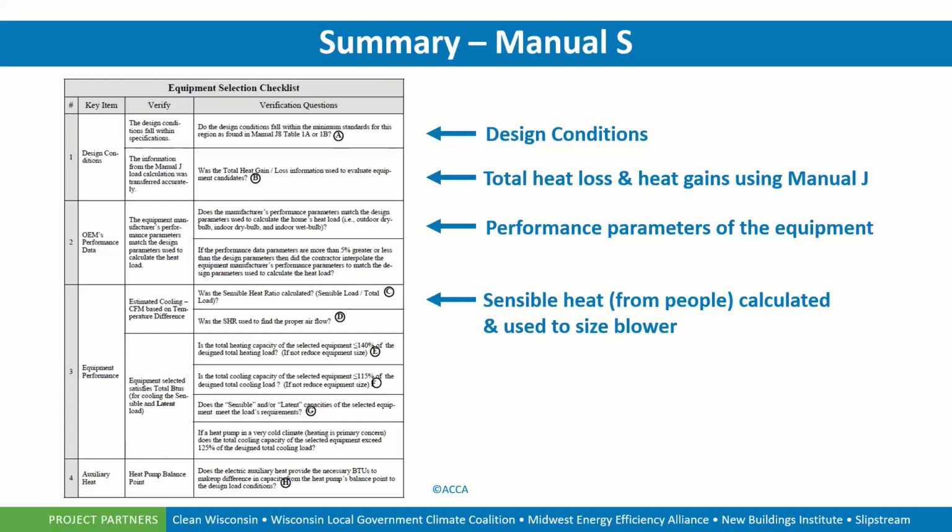So does our furnace, we look at the data for the furnace, does it cover our CFM flow? Does it cover our heating requirements? The same on our cooling side. We pick our heating and cooling plant, the outdoor equipment, the indoor equipment. Does it match with our furnace? Do we get a gain in compliance or testing when we have equipment that's been tested together? So the furnace, the indoor coil, the air handler, and the outdoor unit, they're all tested together.